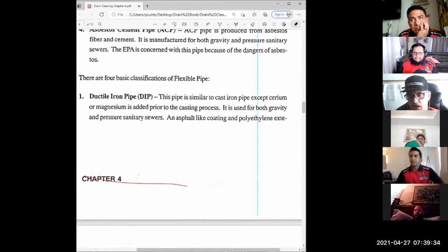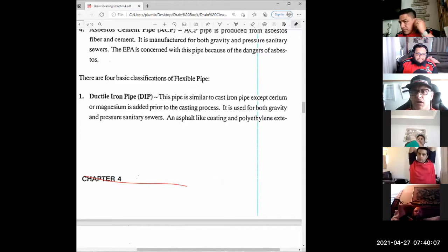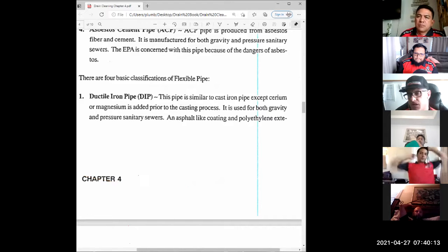Ask anybody who's been around. We have some asbestos pipe here in certain spots on Maui. It's very zone related, time related. In the Kaneohe area, because of the military, they used a lot of Orangeburg, and you'll find some asbestos piping. Darren will probably know more than me about where all that is. Understanding the zones and locations of where things may be in the ground helps with how to deal with the customer. And education is important, so understand what you're dealing with.